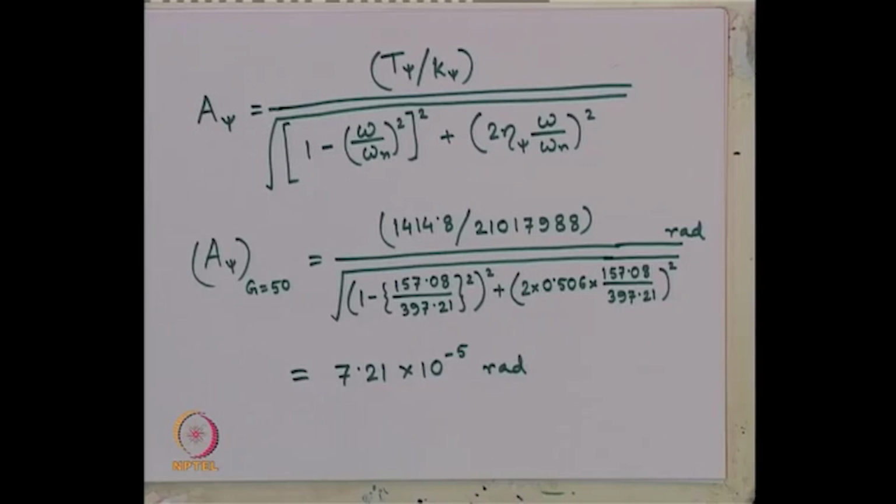That is the way you will get the equivalent displacement in millimeter, and that value should be below 0.2 millimeter. Clear? So, that is the check we need to carry out after obtaining this estimated value of displacement amplitude.